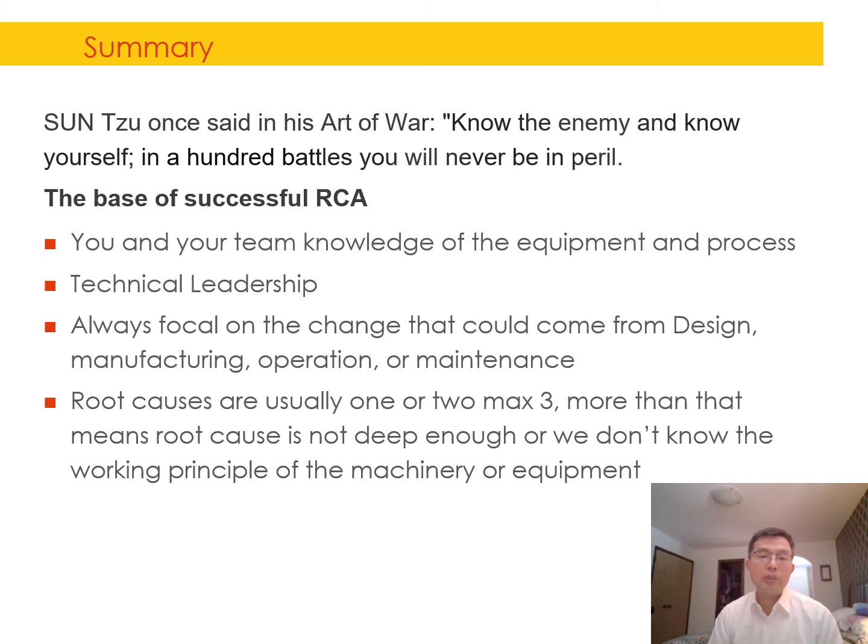Number two, we also need very strong technical leadership here. In the previous case study, the team over there was always working this way, right? First, we asked electrical guys to check, and then we asked the millwright to check everything, and then the instrumentation, then the process. So everybody checked their systems, but they could not find that their system was wrong, right? Only when you look at the whole system and look at how the motor power needed is calculated, then you can find the root cause so quickly. Because in this study, we only needed one piece of data from the operators, the density, right? So it can solve your problem so quickly.